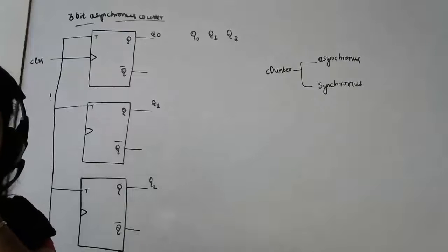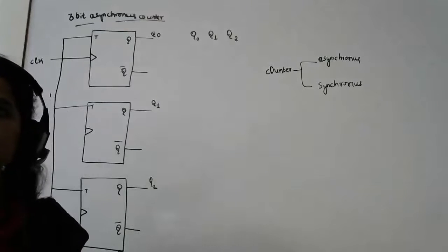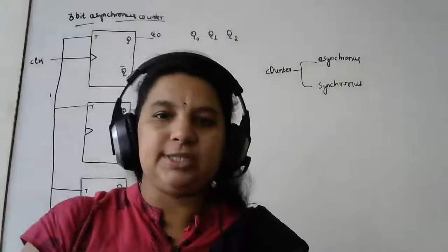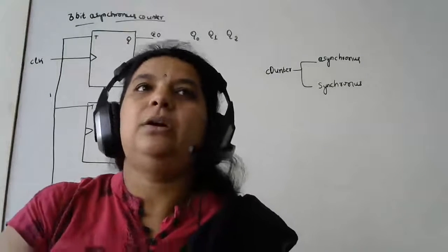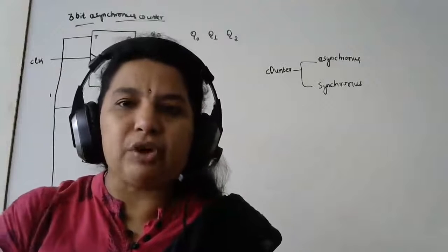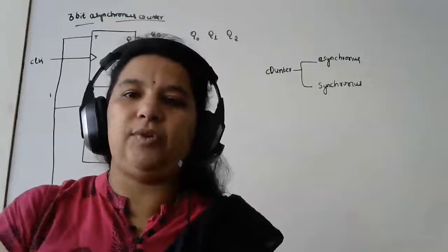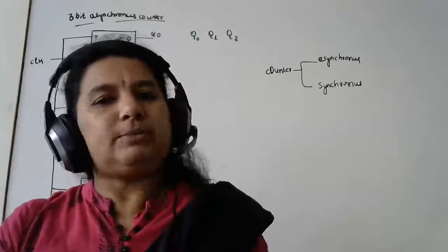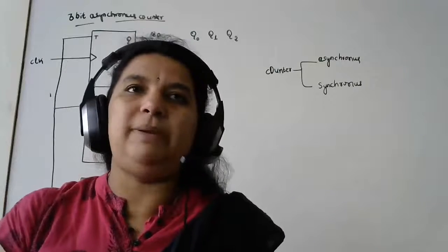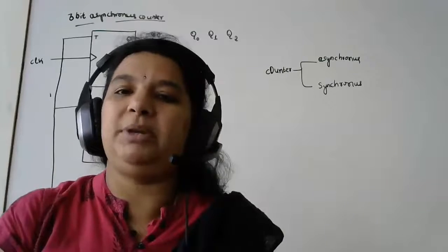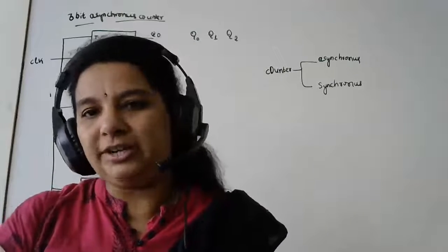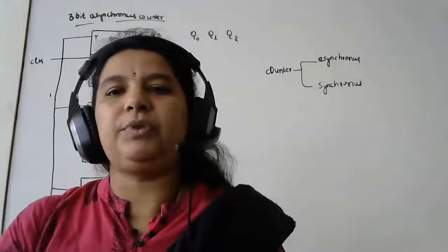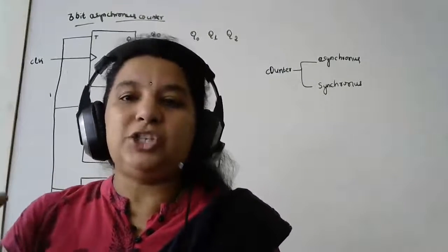Okay, so we are trying to design a 3-bit asynchronous counter. Now, when we were talking about registers as shift registers, what type of flip-flop was I using there? It was a D flip-flop. Why D? Because what was its application? It was mainly used in the memory part of applications wherein I want to store some information. As I want to store and hold the information there, I was using a D flip-flop. Now what's the role of my registers over here?